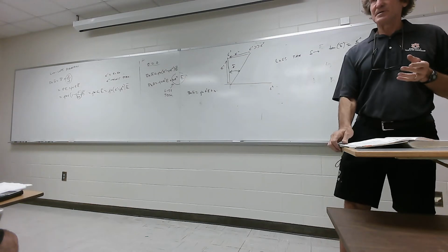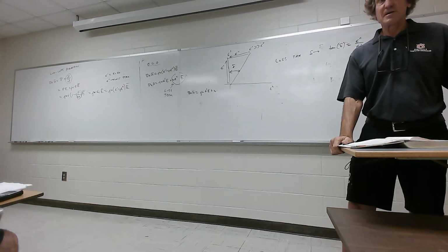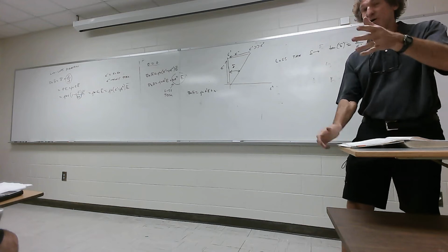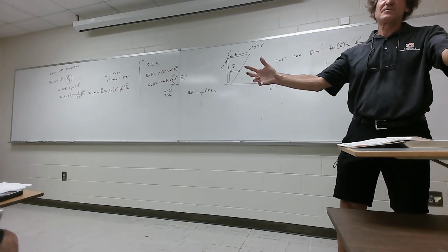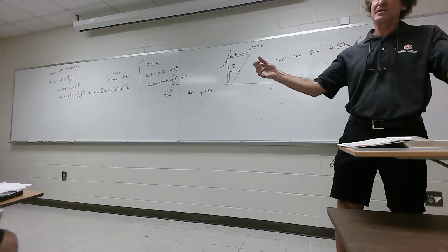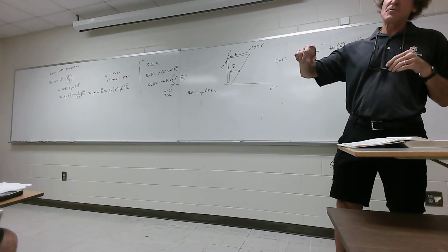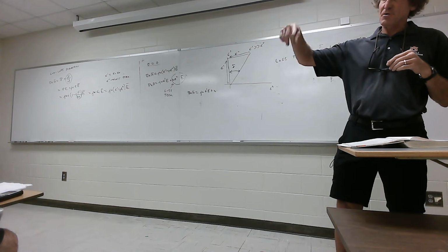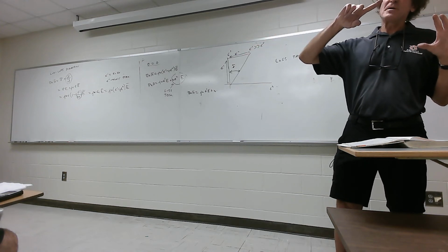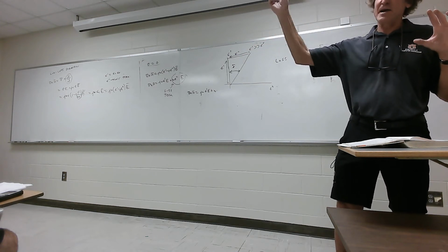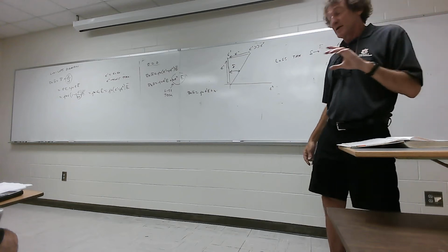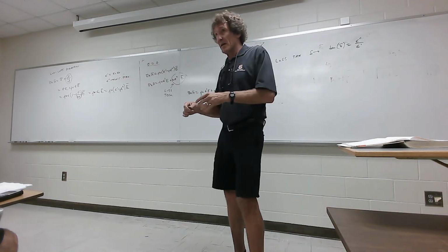And I have personally seen a high energy capacitor that was used for a railgun. I didn't do this, but I saw the thing, it was blown up. Somebody forgot to make sure that current couldn't reverse. You're supposed to have critically damped or underdamped systems in terms of the current waveform that drives it. Somebody forgot that, and they let an underdamped waveform drive the current down on, I think it was a railgun, but I can't say for sure. And it blew the thing up.